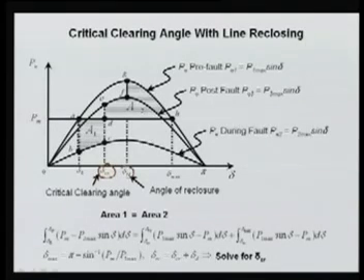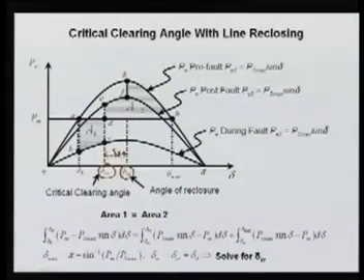Having the reclosing facility, this angle delta D is given to you. It is known because it depends upon the circuit breaker configuration. Automatically it recloses, maybe one cycle reclosing, maybe 1.5 or 2 cycle reclosing. It will wait one cycle and then again reclose. And if the fault is persisting, the circuit breaker will open and it will not reclose again. It is only once. So in this case we want to determine the critical clearing angle. Knowing this facility in our circuit breaker, your fault must be cleared before this angle, otherwise your system becomes unstable.